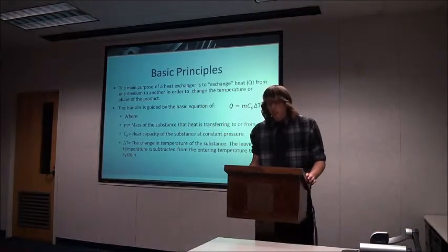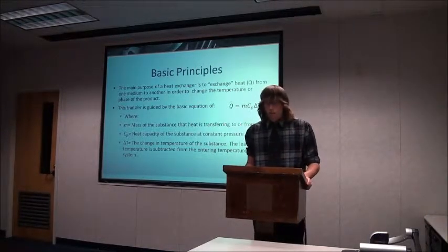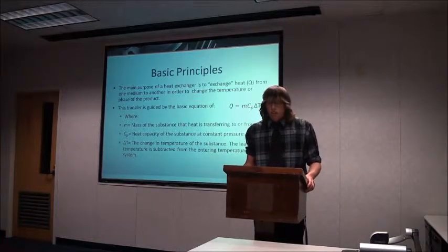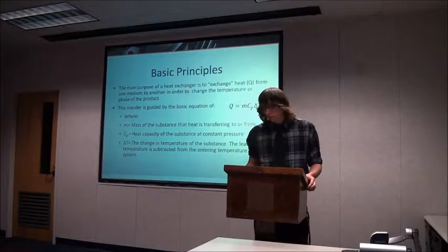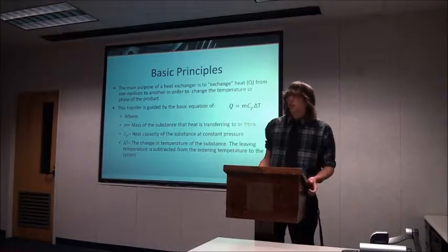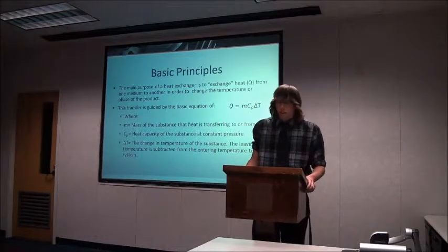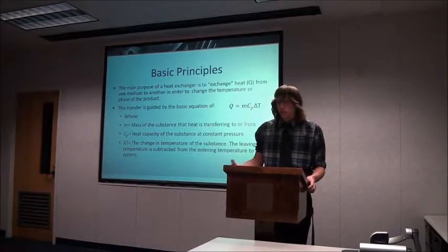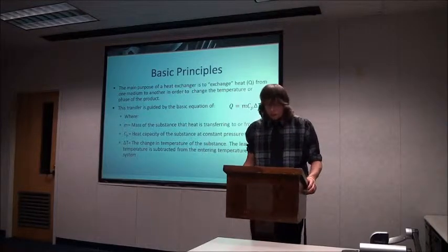Basic principles. The main purpose of the heat exchanger is to transfer heat from one medium to the other in order to change the temperature or phase of a product, like I said before. This transfer is guided by the basic equation Q = mCpΔT, where m is the mass of the substance that's being heated or cooled, Cp is the heat capacity of the substance at constant pressure, and ΔT is the change in temperature of the substance, where the leaving temperature is subtracted from the beginning temperature.